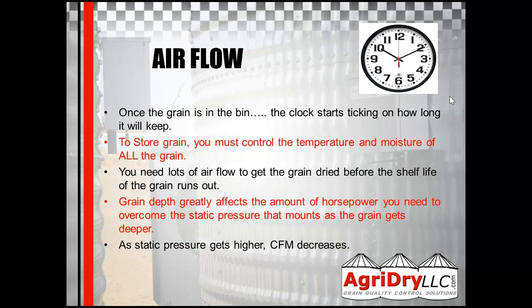So, airflow: what it is. Depending on how much airflow you have determines how fast you can change the moisture or temperature front of the grain inside the grain bin. Once you put that grain in the bin, the clock starts ticking on how long it'll keep. There's a storage life chart, which we'll show in a little bit, for all different grain types. And the higher the moisture and the higher the temperature, the faster it'll go out of condition. So we always have to keep that in mind.